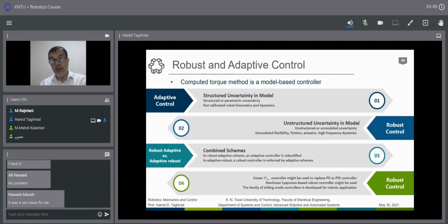And on the other part, what we usually have in robotic manipulation, if you have a nonlinear and multivariable model for the system, then maybe it is difficult to go to the linear controller, the linear H-infinity controller design. This is possible, but it is more difficult. You can go directly to the nonlinear, robust Lyapunov-based controller design, which we will talk about in the next slide.